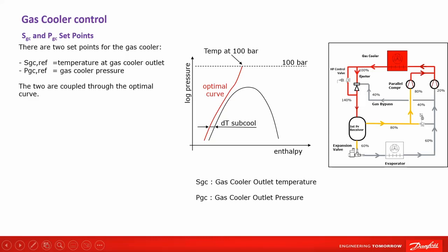Now, please ask the question. Yes, sir. The main thing is mass flow rate. Some part of the mass flow rate will be taken by this ejector as suction flow, and some part will be taken by this MT compressor. Sir, what factor decides this mass flow rate? Because for a certain motive flow, there must be a fixed suction flow for this ejector, and for each compressor also there must be a suction flow, because the compressor is designed for something specific. So how is this mass flow rate divided into those two parts?